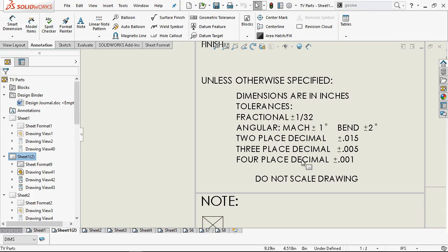Do you want a secondary operation? So 4-place decimal, a plus or minus a thou, with a little bit of caution, I can still get that with a mill. I can still get that with a standard lathe. A reasonably tight machine will produce that tolerance with a little bit of effort. It'll produce decent surface finishes. So, on that end, do I need more than plus or minus a thou? Well, if I do, and I'm doing it consistently, then I would want to apply it here.